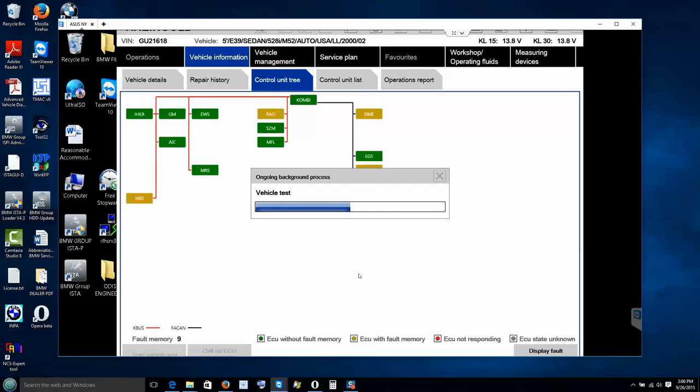The DSC still has code in it. Maybe well on there, we did have 2 codes for it. But we can look at them one day, you know what I mean? And see if it's causing the steering angle sensor not to calibrate properly. But the calibration is a simple thing. So maybe we have to look for other fault codes that have to do with it in the fault code entries and see what we can do with that. We'll calculate a test plan for that one too as well.